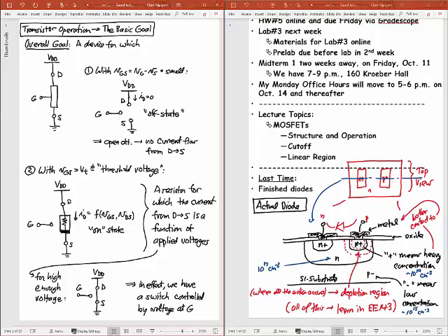I have two terminals, and I want to control what the element is in between them, and I want control through a voltage. So in this case, I've actually put a supply voltage VDD up here. I put ground at the bottom, which means current always goes from the high voltage to the low voltage. So current is going to flow from D to S in this case because of the voltages I put around this. And so with this device here, there's going to be a number of cases that I want. I want to be able to turn the device off. And so turning the device off, to me, means actually shutting down my VGS in this thing. And so I've got a voltage here, VGS.